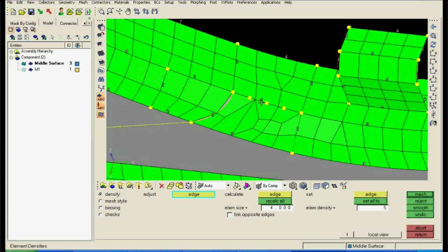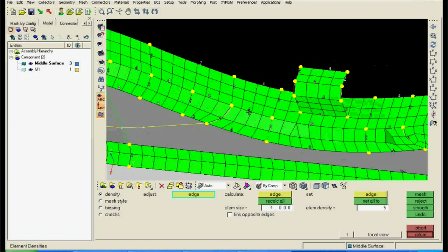Because all you need to do is, opposite edges should have the same number of nodes. Like I can see here 4, so I made this 4 and I made this also 4. So this is what you can try to deal with, and take note: opposite edges should have the same number of nodes. Like for example, here it says 4 4 and the opposite 2. That is nice. I can increase here by one more, I can afford.